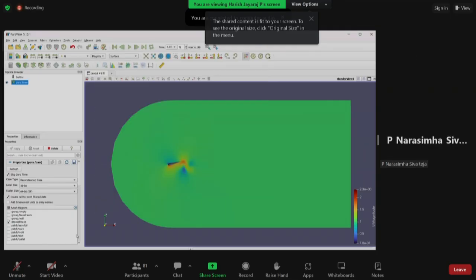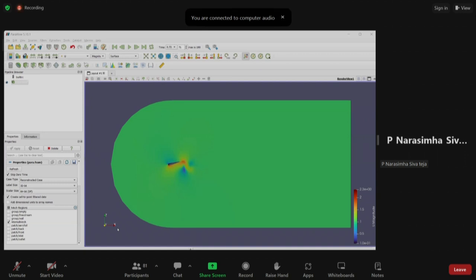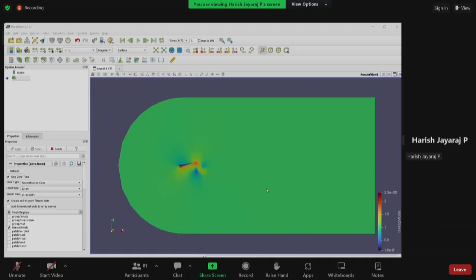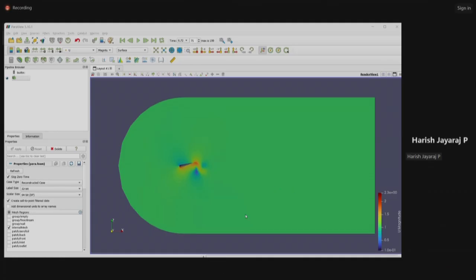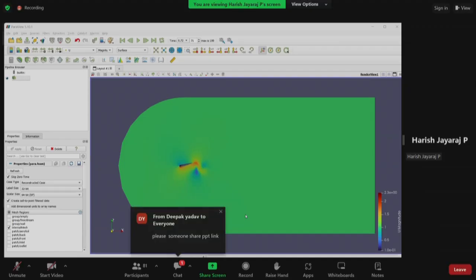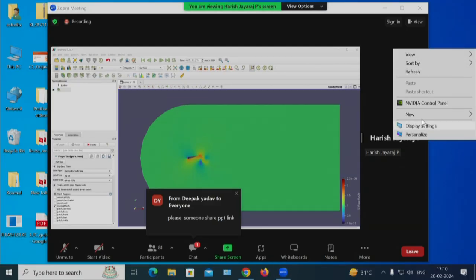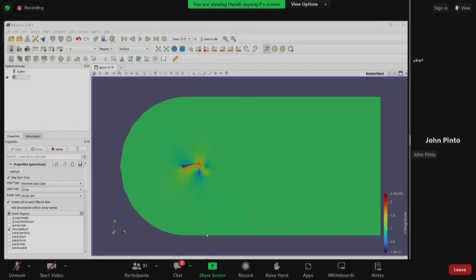Sir, will this code not work in OpenFOAM 7? I'm not sure if the dynamic mesh deck will open. It has interpolating solid body, which works only in OpenFOAM 9. When I tried, it did not work in OpenCFD version. So you can try it. If it doesn't work, it will show you what kind of models you can use on the command prompt itself. So you can try replacing, read the documentation, then you can explain it.